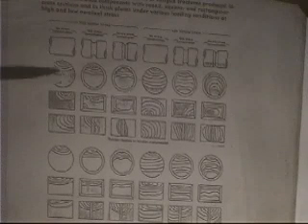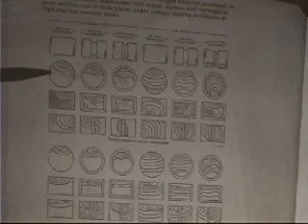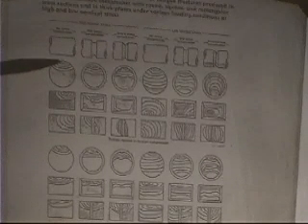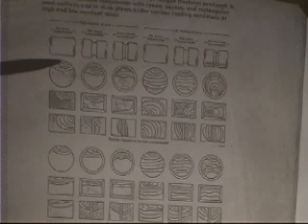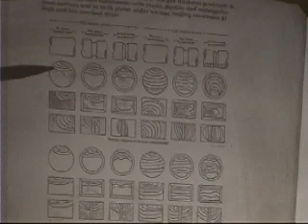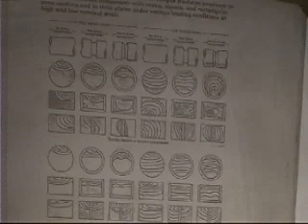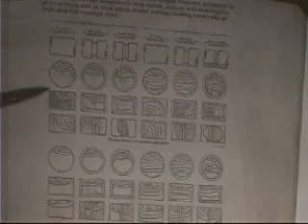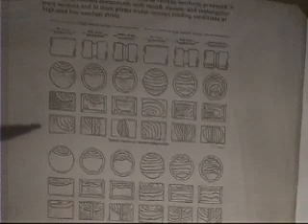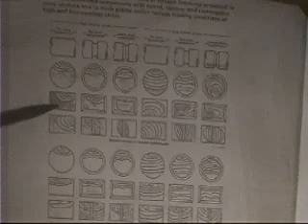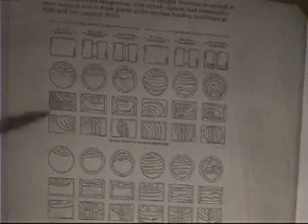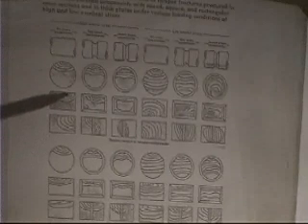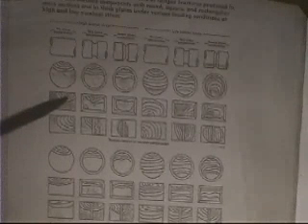So this would be a cylinder under high nominal stress with no stress concentration. The fatigue crack will initiate on the face of the bar somewhere like this, and you'll have these little striations running from here. You can actually see little lines on the fatigue sample. If it's a rectangular sample, it might look something like this. Actually, I could have brought one of those in. Maybe I'll bring one in tomorrow, but these are some aluminum wheels that are fatiguing off on automobiles. But anyway, and it looks similar to this, okay?